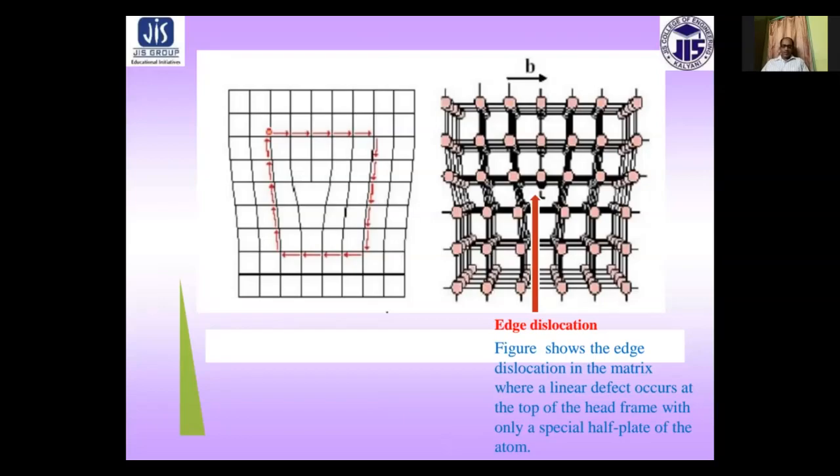The lattice above and below this dislocation line is in a distorted state. For a positive dislocation, the lattice above the line is in compression, whereas below the line it is in tension, and reverse in the case of a negative dislocation. There is more interatomic spacing below the extra half plane of atoms for positive dislocation and above the extra half plane of atoms for negative dislocation, and it favors segregation of interstitial atoms and impurities.